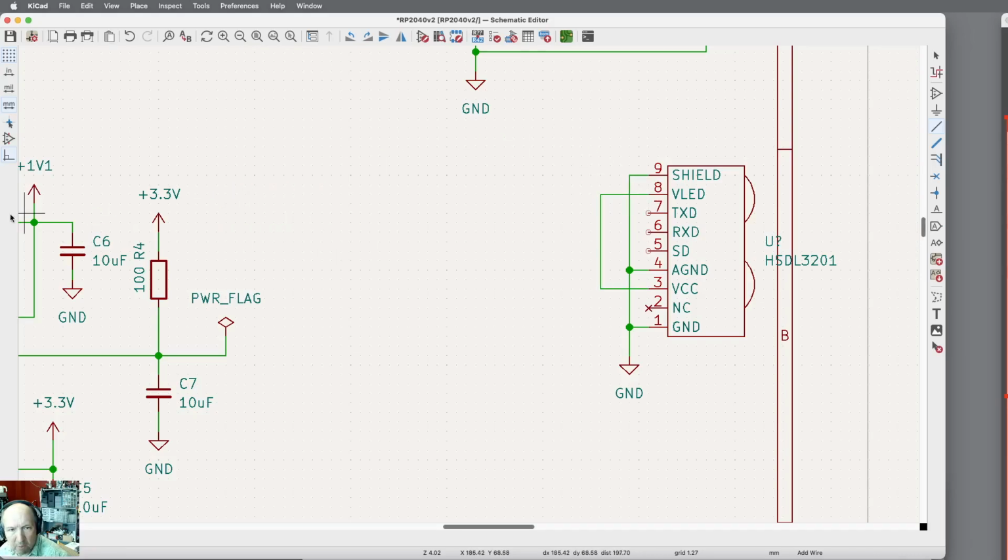And I want the VCC here. So I want to come over here, Command D on that. Put that there. Trace. And I want a bypass cap that's big. I want the 10 microfarad cap that we've got right here. I'm going to hit escape again so it erases that.